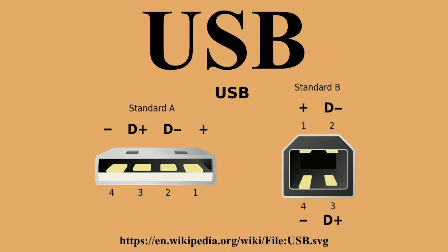Full-featured USB Type-C cables are active, electronically marked cables that contain a chip with an ID function based on the configuration data channel and vendor-defined messages from the USB Power Delivery 2.0 specification. USB Type-C devices also support power currents of 1.5 A and 3.0 A over the 5 volt power bus.